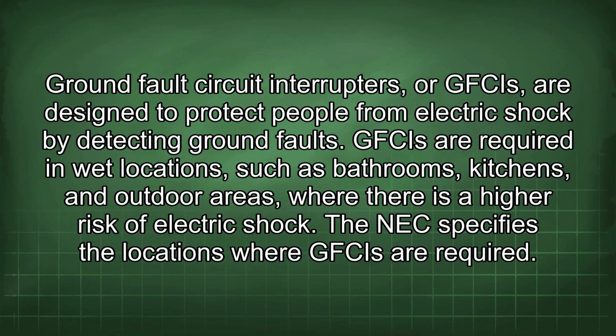Ground fault circuit interrupters, or GFCIs, are designed to protect people from electric shock by detecting ground faults. GFCIs are required in wet locations, such as bathrooms, kitchens, and outdoor areas, where there is a higher risk of electric shock. The NEC specifies the locations where GFCIs are required.